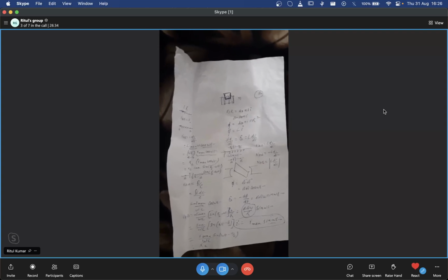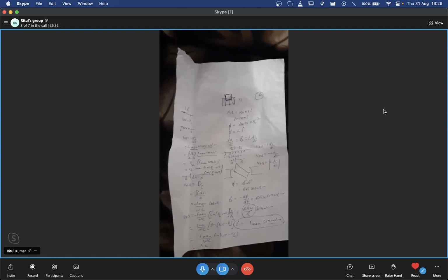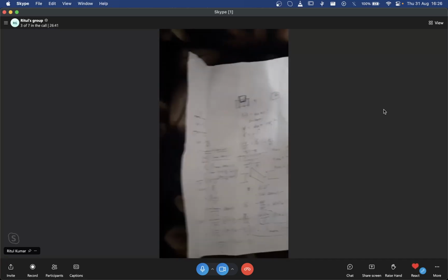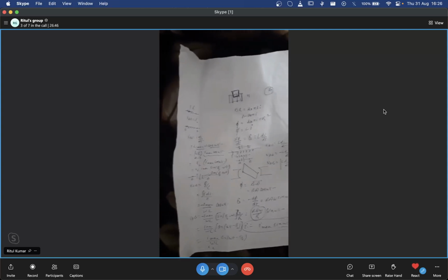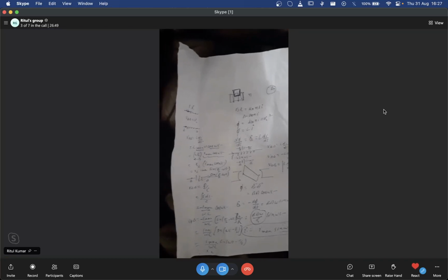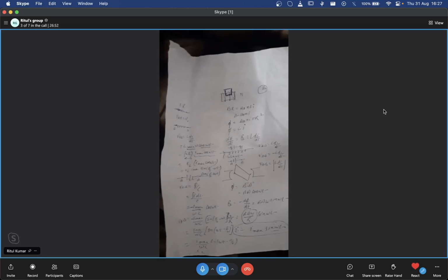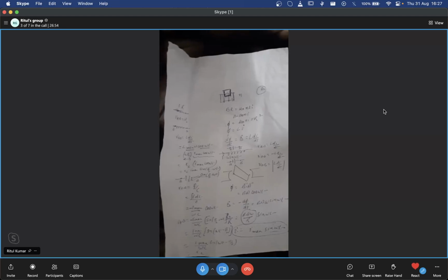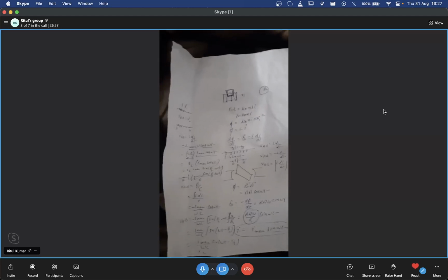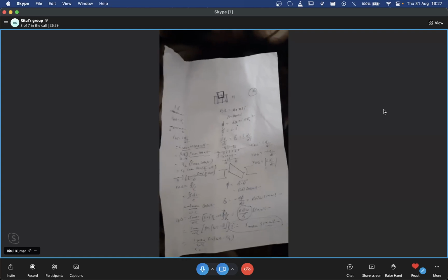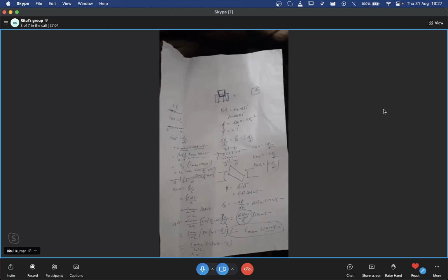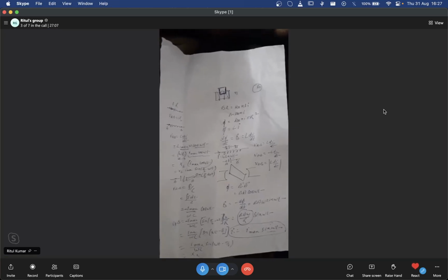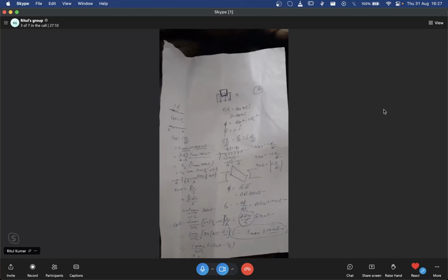If someone is asked on the difference between reactance and resistance, the only way to differentiate is that resistance will always oppose the flow of current. Current increasing, current decreasing, whichever mode the current is in, resistance will oppose it. But reactance opposes change in current. Resistance opposes flow of current. Reactance opposes change in flow of current. Clear? Reactance opposes what? Change in flow. So I can follow that logic with an inductor, but that does not seem to be the case for a capacitor, does it?